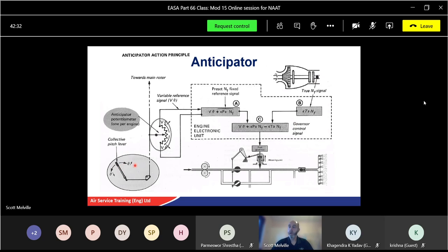It's just sensing the speed, and it will maintain the speed of the LP turbine depending on what the pilot is doing. And likewise, if the pilot wants to go down, he's going to decrease the pitch. Like in module 17, if you decrease angle of attack on a propeller, it's going to speed up. So we don't need all that fuel. If he's decreasing the angle of attack, then unless we change the input to the fuel pump, there's a chance that the free turbine will overspin, which will overspin the gearbox and so on. The rotor will go too fast.